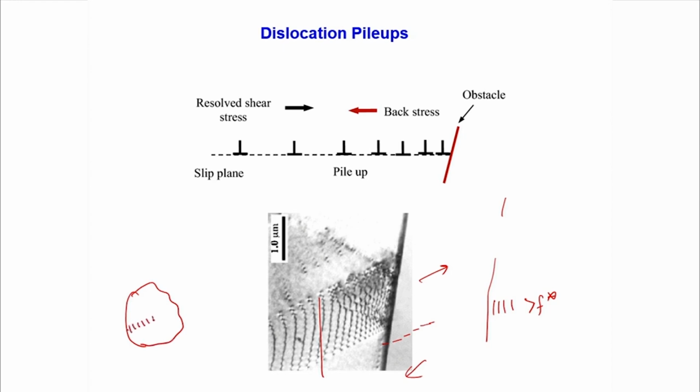They just move, you can see that, and then reach this grain boundary, and there they find an obstacle present to cross over or to cut over, and that's why they cannot move. Okay. So that means what? Dislocations can be piled up if there is a grain boundary in front of them.